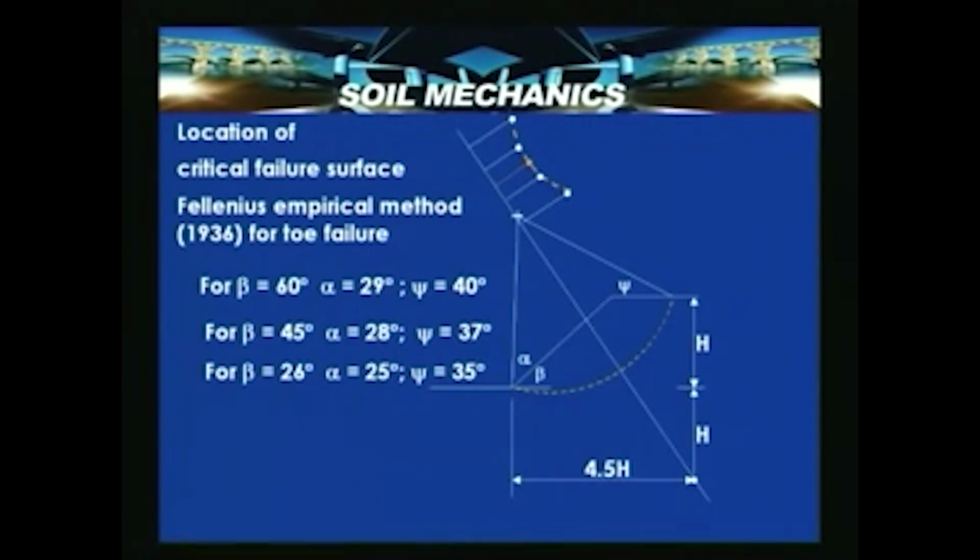Based on that, a number of failure surfaces can be generated. Once it calculates the factor of safety of all these failure surfaces, the efficiency of the program depends upon the one which correctly gives the lowest factor of safety. That happens to be the possible failure surface which can actually occur for the given section being analyzed.